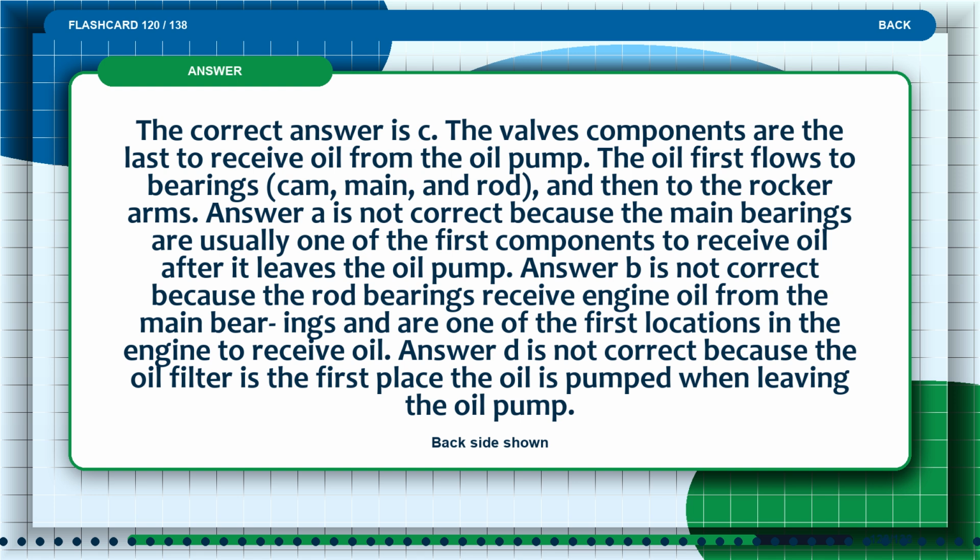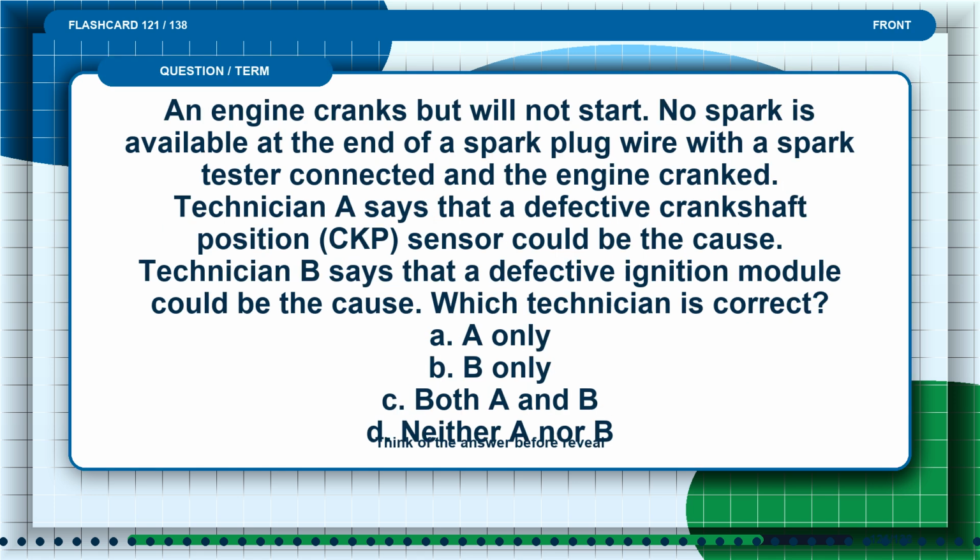Answer B is not correct because the rod bearings receive engine oil from the main bearings and are one of the first locations in the engine to receive oil. Answer D is not correct because the oil filter is the first place the oil is pumped when leaving the oil pump.